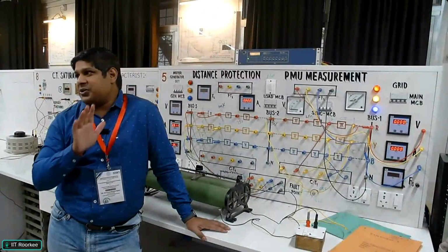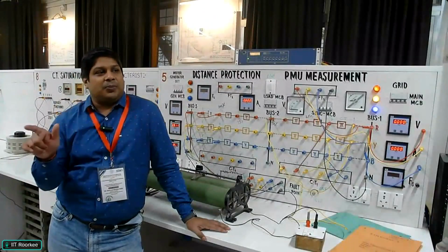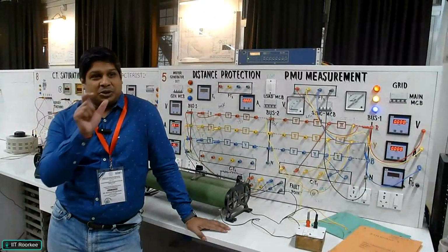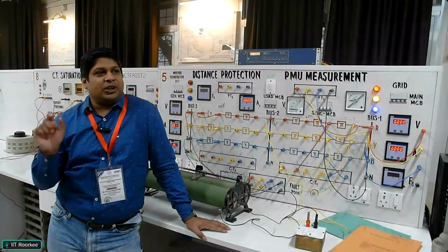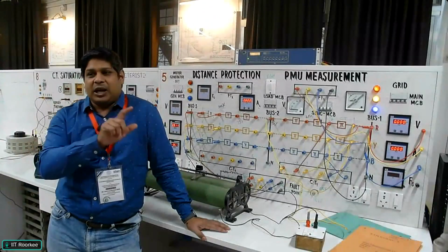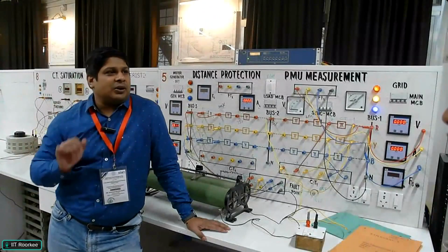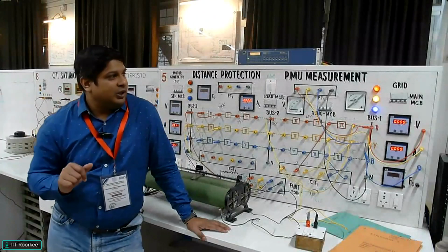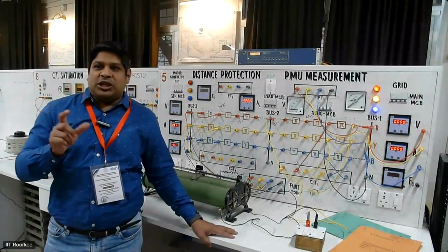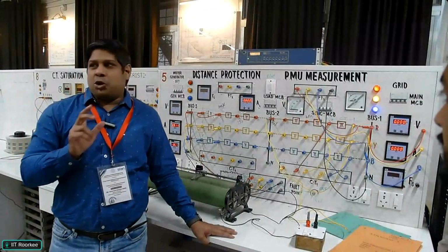So it comes under the second zone. R1 will wait for R2 to trip. That delay which we gave is us waiting for R2 to trip. If it is still not tripping, after delta T1 time, R1 will trip and it will isolate the problem. And similarly like this. The relay which we normally use in distance protection is the Mho relay.